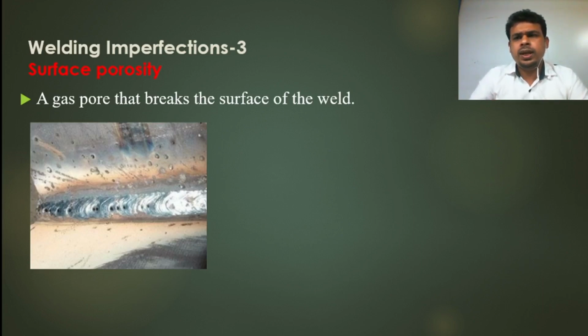So it looks the same, but there are some different terms and different definitions. You can see that if the gas is already inside the weld and comes out until the surface, then it breaks the surface. So this is called the surface porosity.